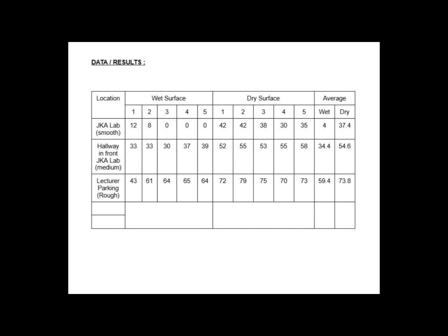So as we can see, the average for wet is always lower than the average for dry in terms of the skid resistance value. This is because when there is water or any lubricant, it reduces the friction between the rubber and the ground, so the skid resistance value will decrease, because skid resistance value basically measures the friction, how strong the friction is between 2 surfaces, and therefore if you add water, it will obviously lower the friction value. And the wet surface is to simulate rainy situations on a road where vehicles travel.